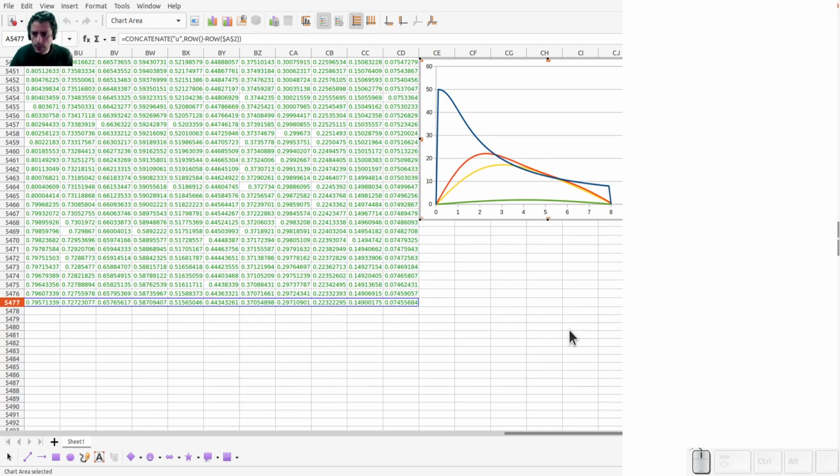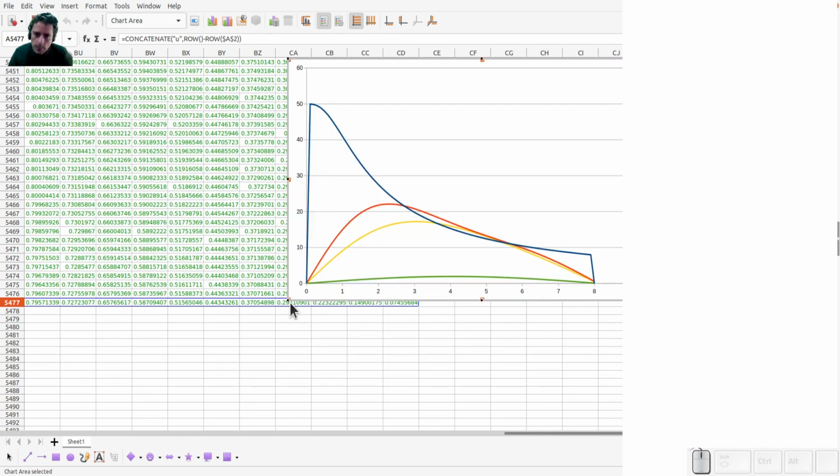So let's finish for now. So we see here the variation of pore pressure with depth over time. After 15 years, we still have some pressure, although it has been significantly reduced. Okay, and that's the profile with depth, after different periods in time.